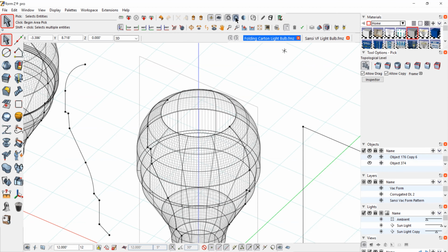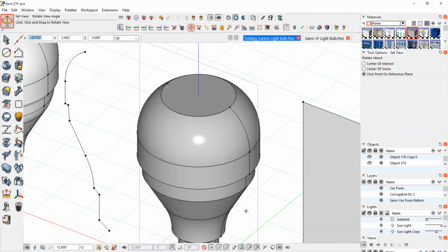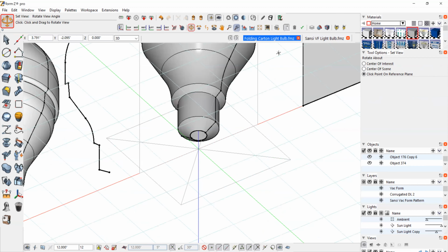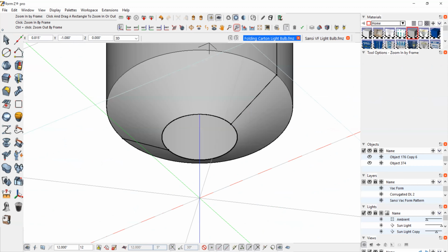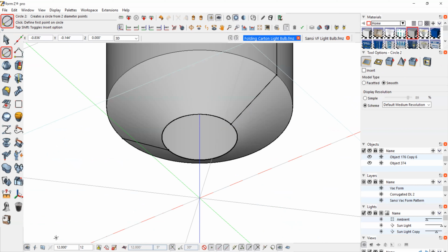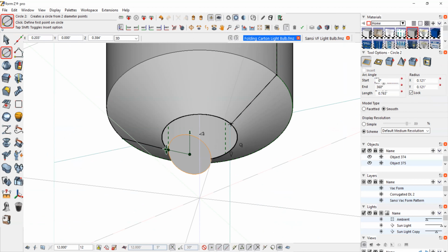Let's go to interactive shader, and you can see I have this part now on the top. That would have to be done on the top and the bottom because I did not include that in my revolve. I actually prefer to do that. I don't want to revolve on center. I want to revolve and then add my closure later. So I'm going to do the same thing down here, to make sure I'm on horizontal. I'm going to click on that point, and, oh, this is not horizontal, so that's not going to work. Hold on.